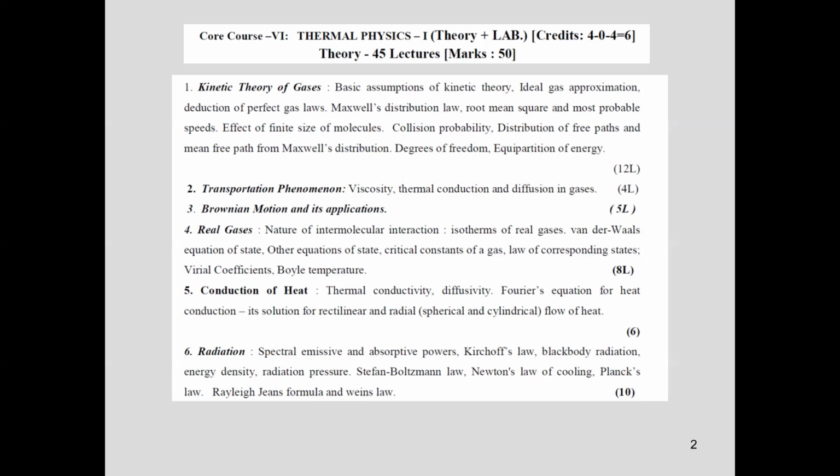Now, you need to have some understanding of the first few things, but I think you more or less have the basics, and I'll continue with the conduction of heat, where we need to understand thermal conductivity, diffusivity, and the Fourier equation for heat conduction. So basically, it's a mathematical model for understanding heat conduction, and also the application of this in various frames of reference like spherical or cylindrical structures for the flow of heat.